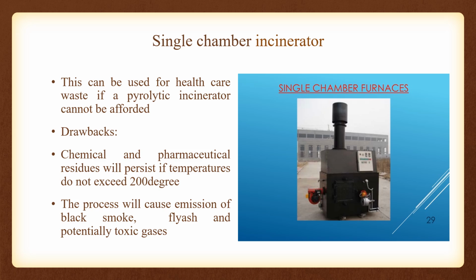A drum or field incinerator is the simplest form of the single chamber incinerator. A 210-liter steel drum is used with both ends removed. This will allow the burning of one bag of waste at a time. A fine screen is placed on top of the drum to prevent some of the ashes or light material from blowing out.